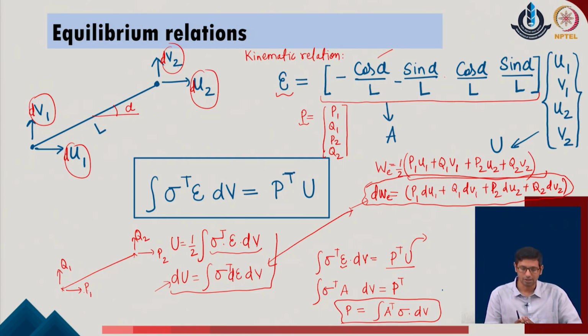Now, this relationship we have earlier also defined for the general beam kind of a relationship. If you recall the truss member, we have also expressed this relationship in the form P equal to A transpose S, because we realize that the stress inside a truss member remains constant. So, even if you do the integral of this stress component, you end up with S, which is the axial force of the given system.